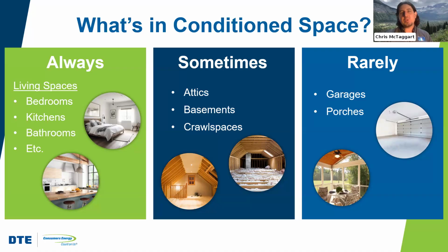The reason why is because crawl spaces tend to have a lot of moisture in them that comes up through the ground. So in a lot of ways, it's better to have a really airtight barrier at the floor of the crawl space, same thing up the foundation walls without vents, and then to seal and insulate those walls and the rim joists of that crawl space so as to bring the crawl space into conditioned space.